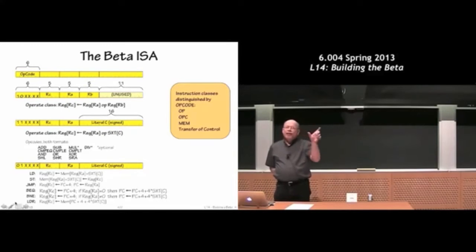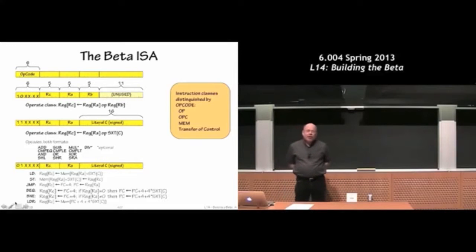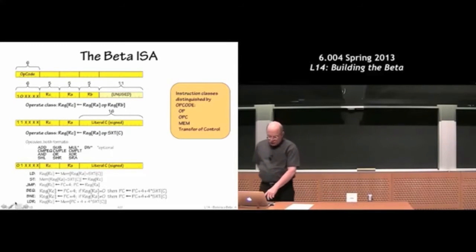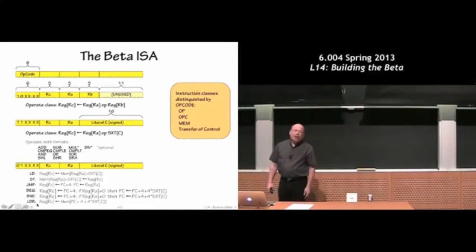They let us load information to and from main memory and the registers. So that's load and store. And then there's 3 instructions, jump, branch equal, and branch not equal, that let us change where the next instruction comes from in memory. Normally we're just fetching instructions sequentially from memory, but we can change that with the jump and branch instructions. And finally, there's sort of a weird instruction called LDR that you'll talk more about in a section.